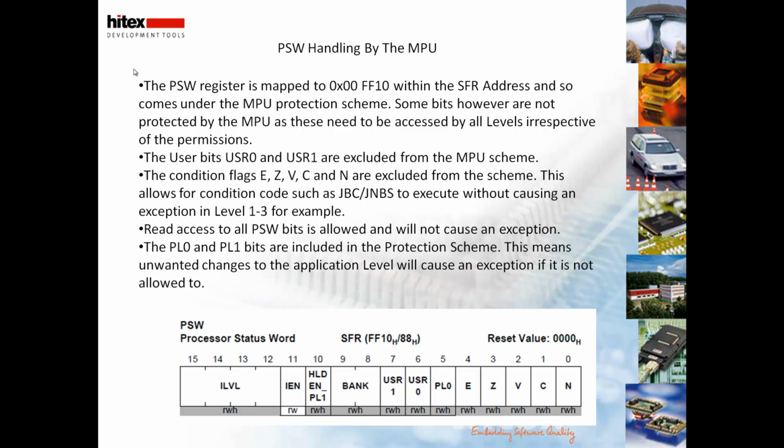And the way to do this is actually to use a RETI instruction. The RETI instruction is powerful in so much as if you have the program status word already on a stack and you do a RETI instruction, then basically you pop off the PSW word as well as a memory location address. So we could actually transfer both program control and also change the level by careful manipulation of the stack and the values which are on there, and then executing a RETI instruction.